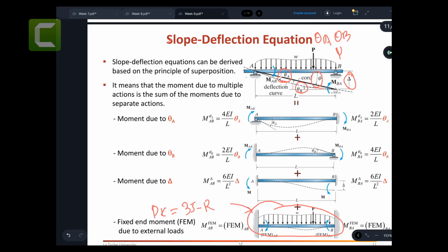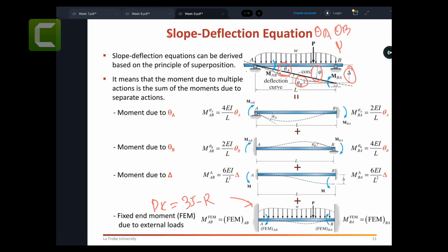So what is the kinematic degree of indeterminacy for this structure here? By the way, those two ends are fixed. These are fixed at A, fixed at B. The kinematic degree of indeterminacy for this structure here. So do you agree that this kinematic degree of indeterminacy would be 3 times the joints, which is 2, minus the reactions, 1, 2, and 3, 1, 2, and 3, that is 6. So that is 6 minus 6. So that is 0. So you have 0 kinematic degree of indeterminacy.